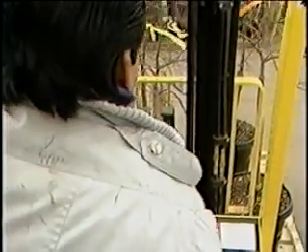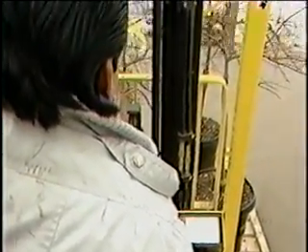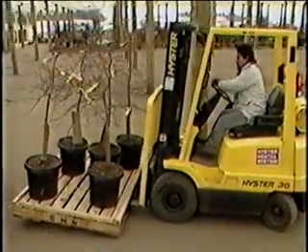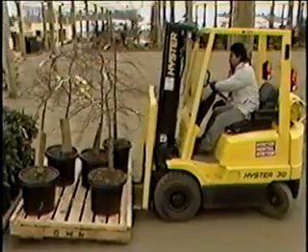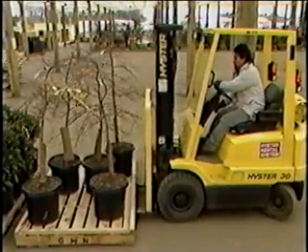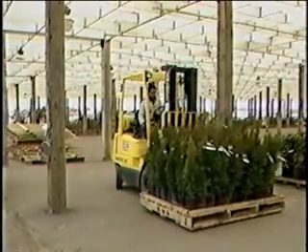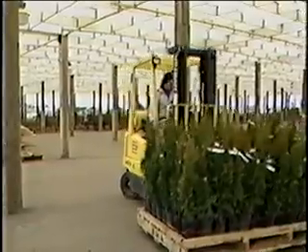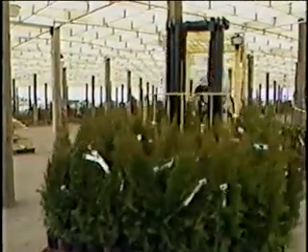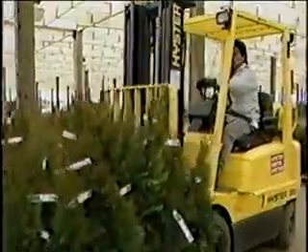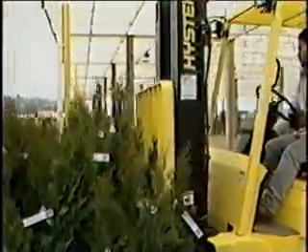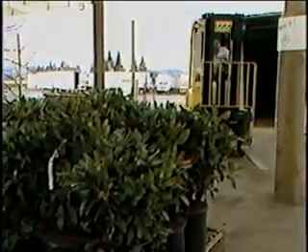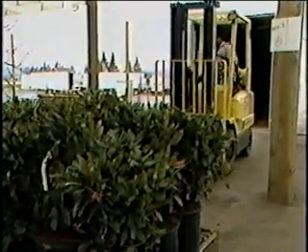A load that is not properly secured or stabilized will tip or fall off the forklift. If this happens while being moved, the result can be serious damage to the material and possibly serious injury to people in the area. Remember that you, the operator, are responsible to know the proper load capacity of your forklift. You are also responsible to know how to properly place and secure the load in order to ensure safe handling of material. If you ever have